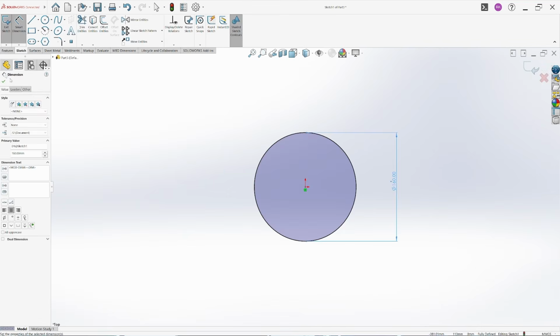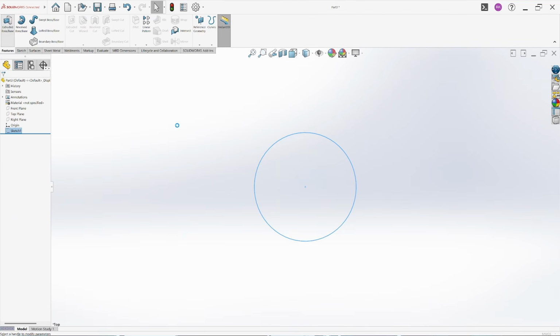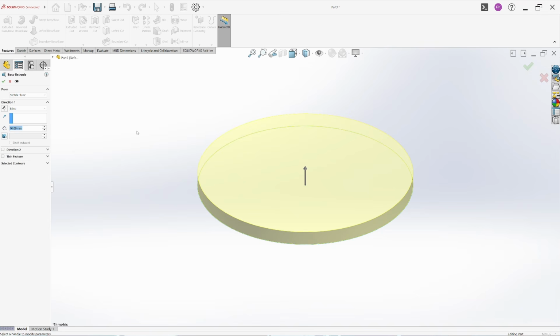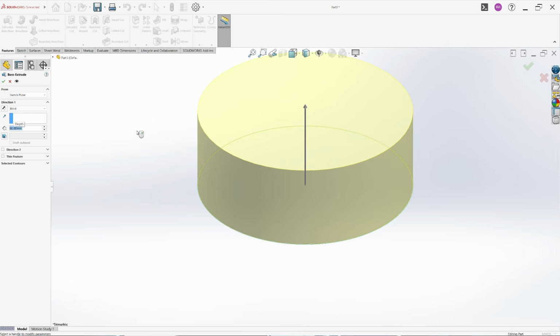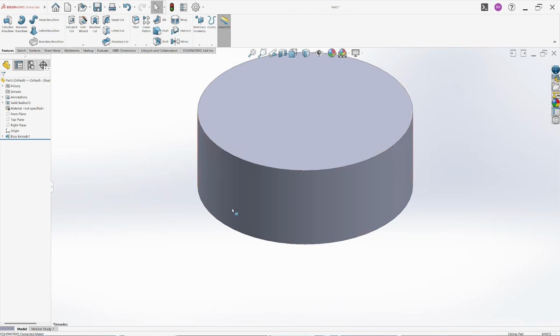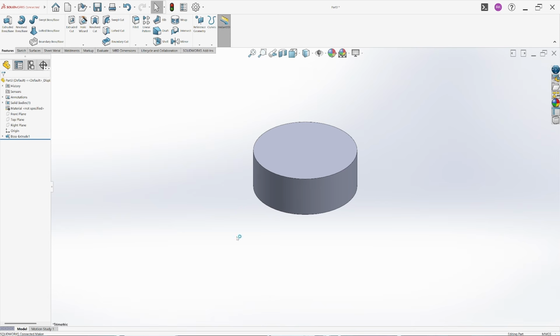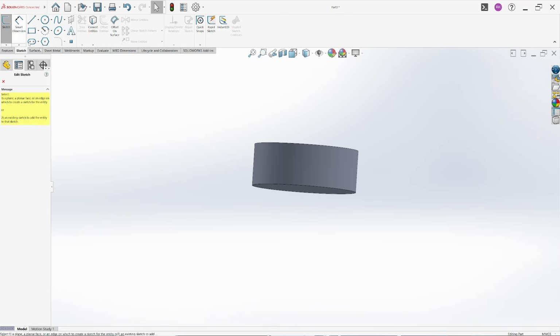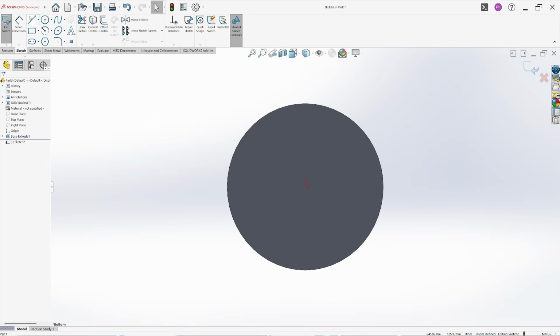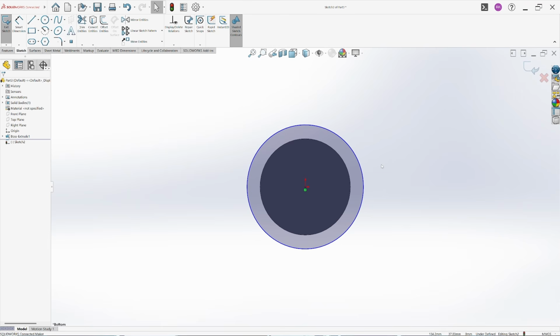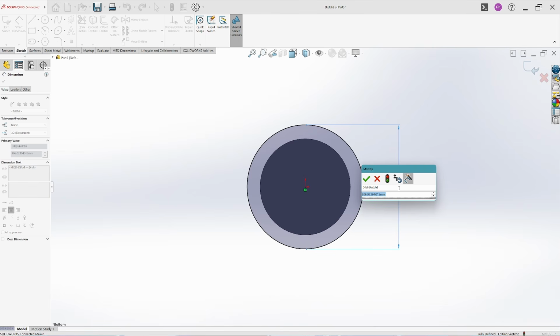Okay, and let's take the extrude command and the height. So the depth of the final product is 60 mm, so set it to 60. Okay, now we need to take a step right here. So let's take a sketch again and sketch on the bottom face of the punch and select a circle, start from origin. And now what would be the diameter of this step?